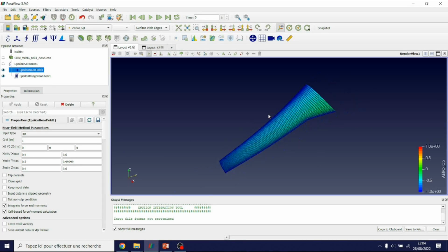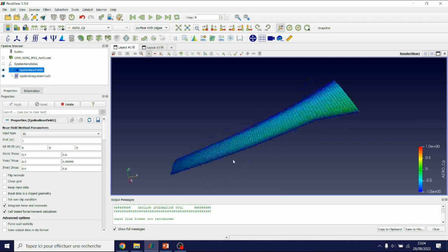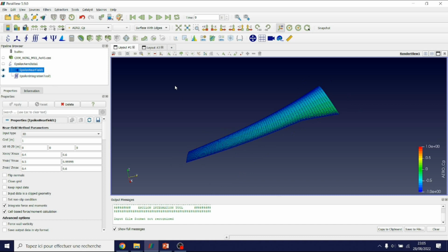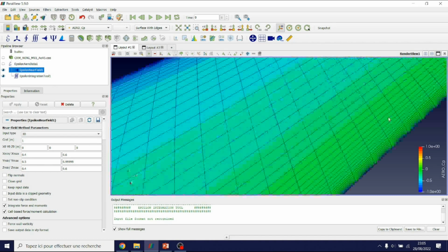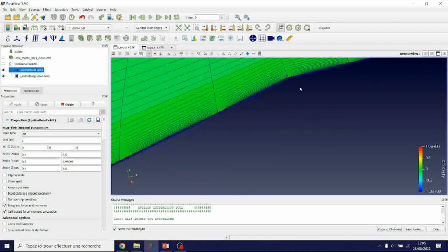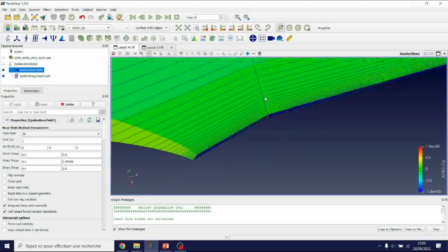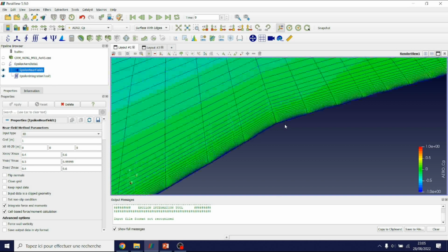But now I just want to generate a line lying along the trailing edge of the geometry. Well, you can do it in two ways. One way is, as I mentioned before, you click on the plus button to add the selection, and you click here and select points on, and then you have to select one point at a time, but it's quite difficult in this kind of mesh because, as you can see, I have selected multiple points, and this is not what I want. I really want just to select one point here, so I will delete this.